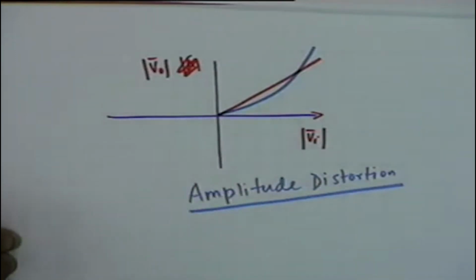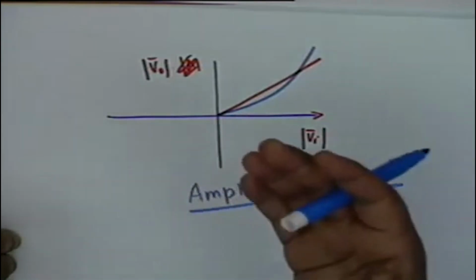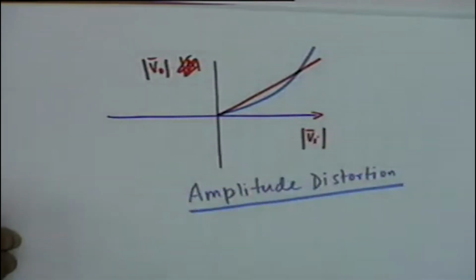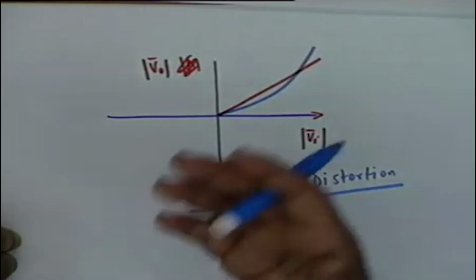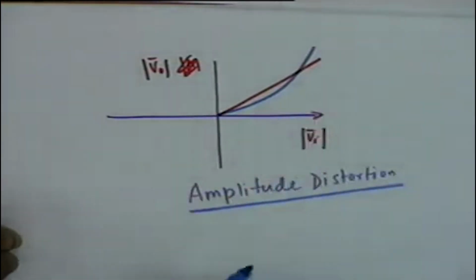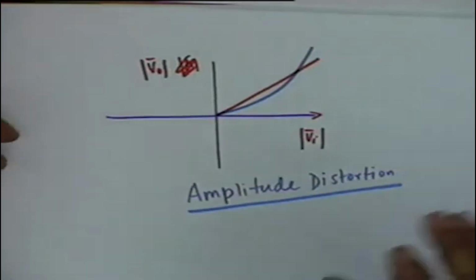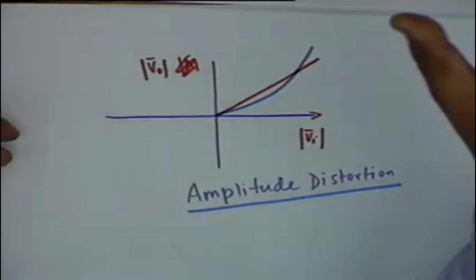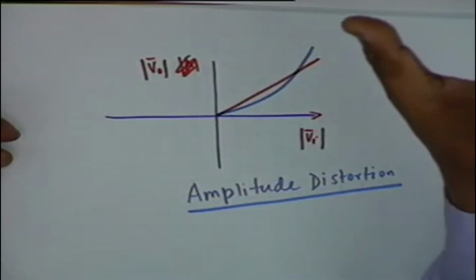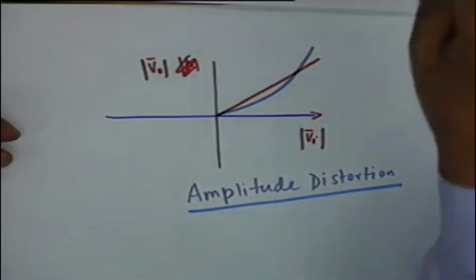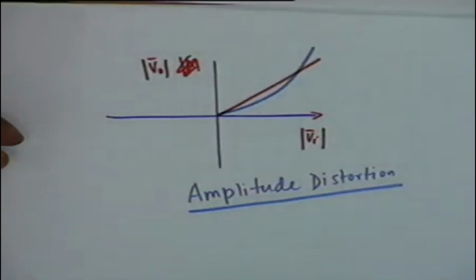For musical reproduction, we require a very, very good linearity of amplification. On the other hand, speech, most of it is not paid attention to, so somebody speaks, that's about it. And there is a large crowd. The actual content of the speech is not important, and therefore a lot of amplitude distortion is tolerated in a public address system. It cannot be tolerated in music.